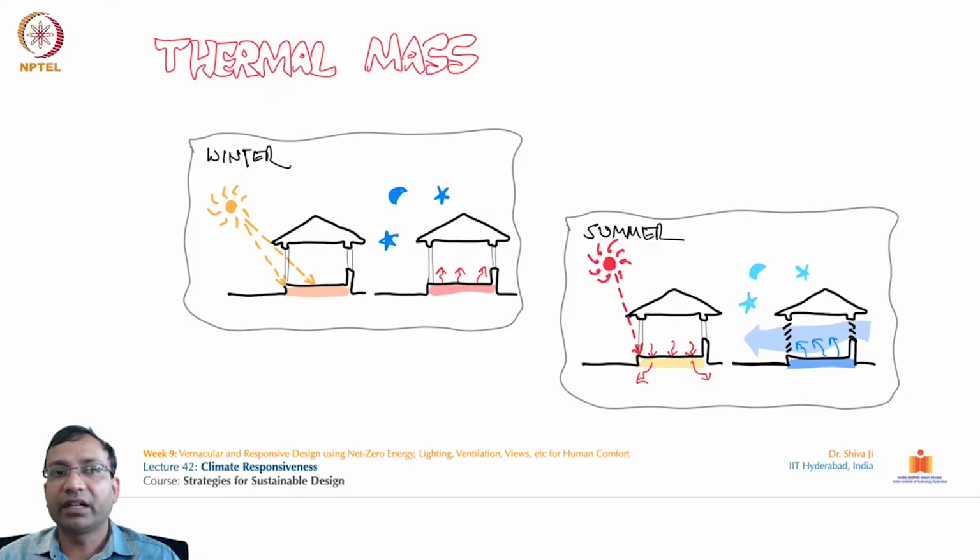So yeah, these aerated autoclaved concretes, you can see AAC blocks over here. This has a thermal mass storage capacity of 550 kilojoules per cubic meter Kelvin. So this is one of the preferred materials in recent times, which utilizes the industrial waste output of fly ash in making a bulk of these AAC blocks.